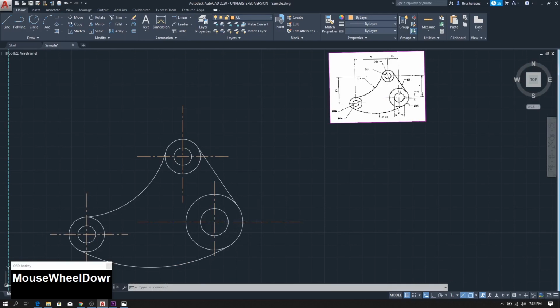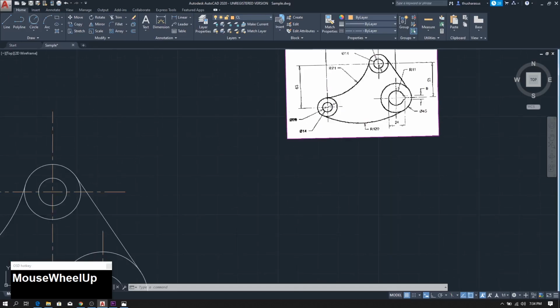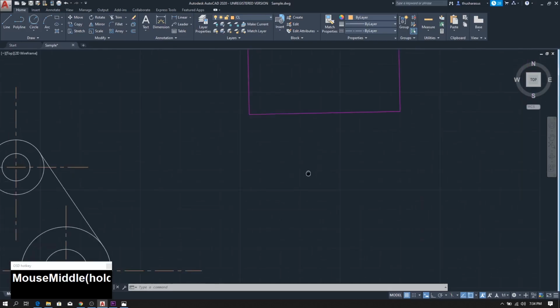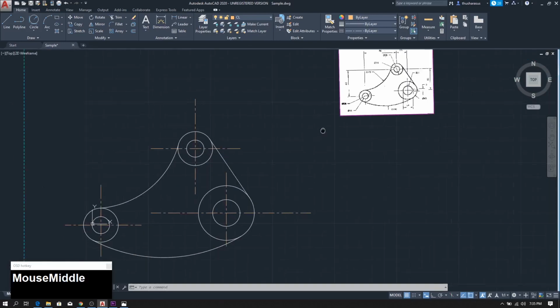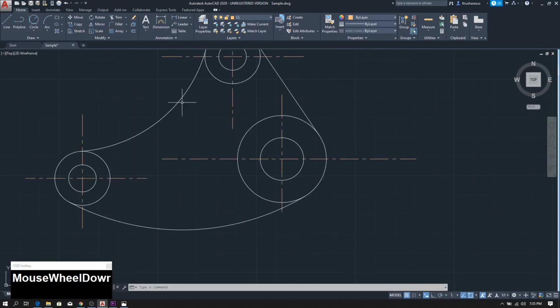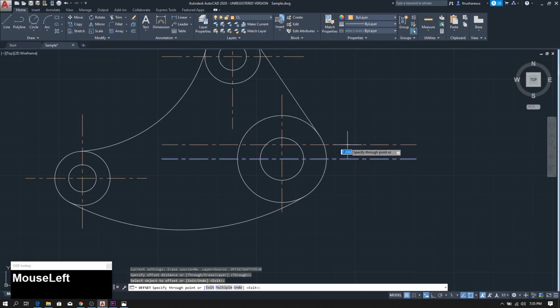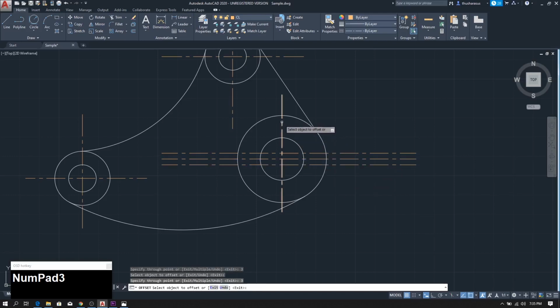image, but in here we have a rectangular shape. To draw that, we can create some construction lines. That line is located from here to here, maybe 13 millimeters. The distance is 13 millimeters, and the height is 6 millimeters. To draw that, let's take the offset command and enter. In here we have to draw 3 millimeters above and 3 millimeters below the center line, and then we have to draw this line in here at a 13 millimeter distance.